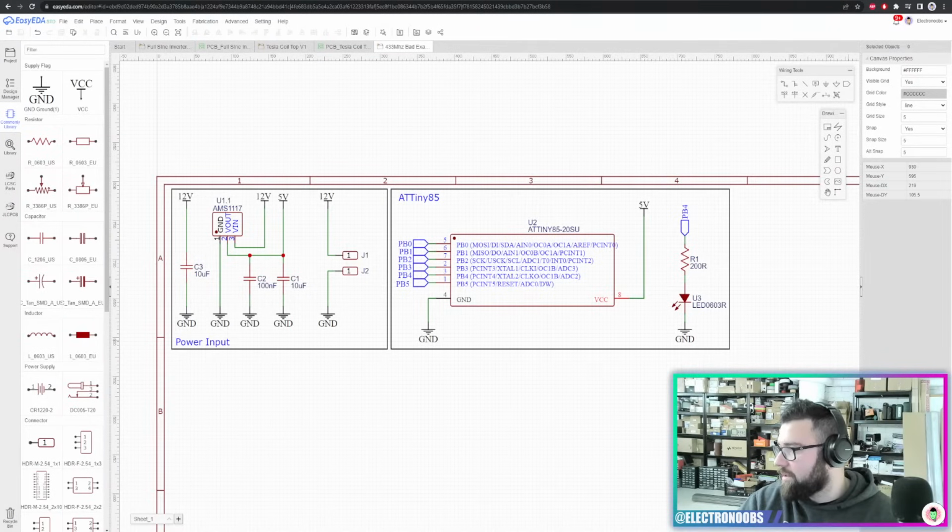Okay, next question. Please continue the series about the smart solar charge controller. Yeah, that was a bummer because the solar panel controller was meant to be an MPPT, but finally it ended up like a PID controller for voltage. Basically, an MPPT should measure the input current and the output current, and always try to maximize the power that goes from the panel to the battery. And that project kind of did that, but not perfectly, and it ended up being something like a PID controller.